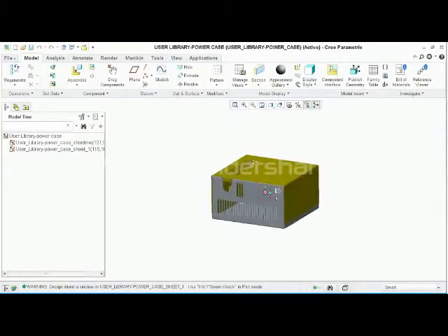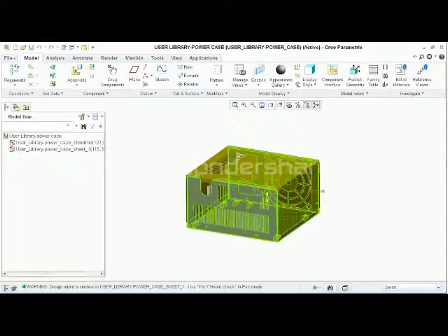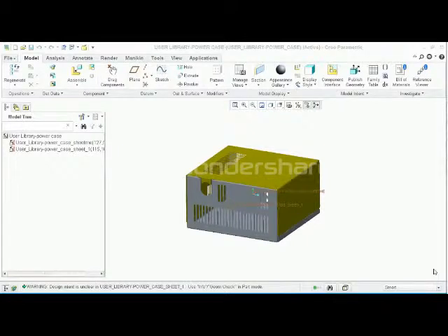So the idea here is, I'm working in Creo. I need to make these modifications in Creo. Problem is, in the past, when you bring in dumb geometry, there's really not much you can do with it. When you import geometry from another CAD system, you don't have a lot of flexibility in terms of the changes that you can make. But with flexible modeling, I actually do. So I'm going to make some changes here.